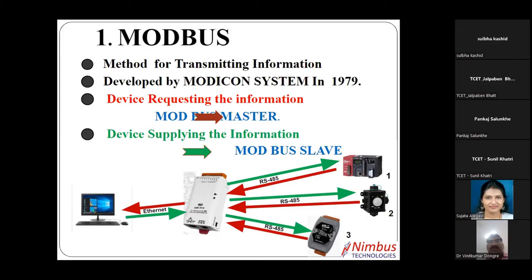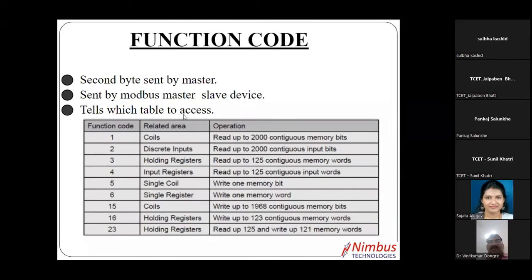So I come across these points also. If the data from the sensors or slave modules is digital, that data should be stored in the coil register or contact register. The function code indicates which type of data the host wants to read.